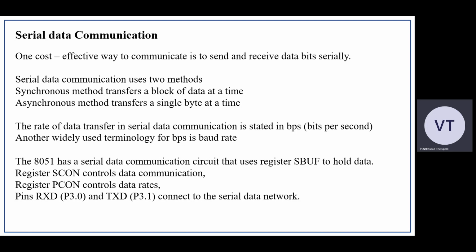Depending on your application, you have to select such microcontrollers, and for that you have to spend a little more. If your application doesn't demand analog to digital and digital to analog converters, don't go for such microcontrollers. Confine yourself to microcontrollers having ports, timers, and serial communication.